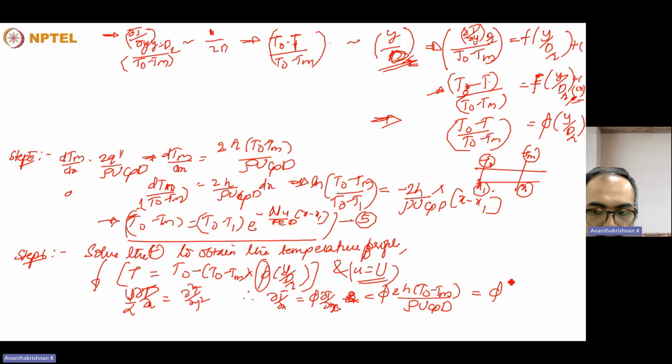That is Nusselt number into alpha; you just multiply by d on the top and the bottom, as well as k here and there. We'll get Nusselt number, k is the conductivity, and then one alpha term in the denominator, T0 minus Tm, and you can arrive at this form by doing some manipulation. This is nothing but mathematical simplification of the original equation in terms of dimensionless variables.